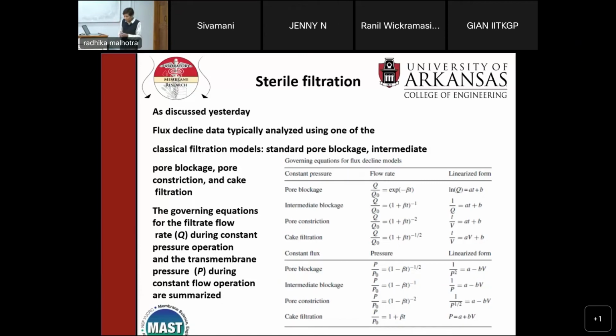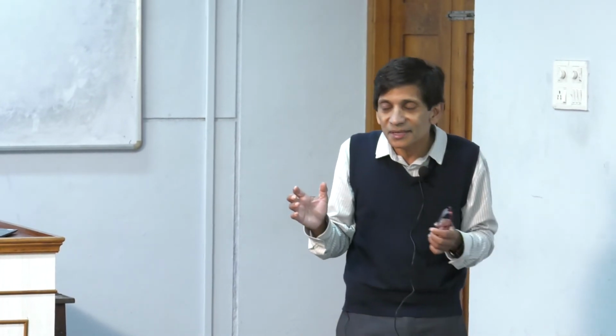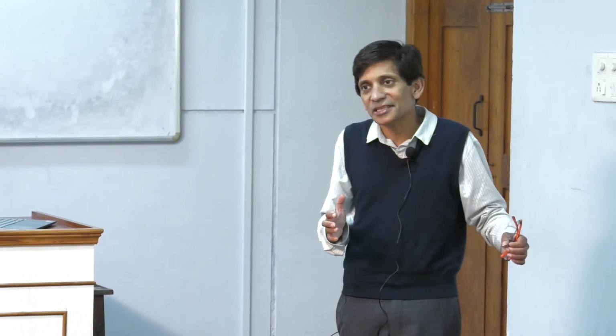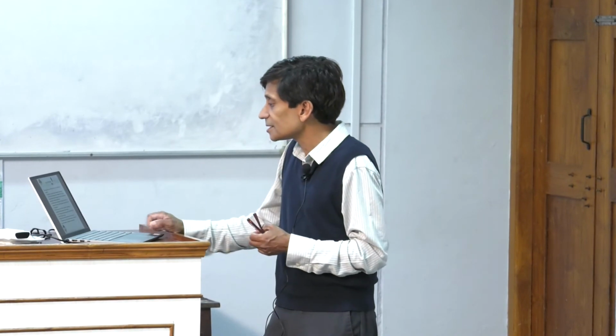Okay. Another thing to remember, in batch processing, you cannot change a filter during a batch. It's not sterile, right? It's impossible. So you have to size your equipment so that you can process the whole batch, because if you don't, you're going to lose the batch, and that could be millions and millions of dollars. That's huge. So often these are designed with a lot of redundancies, but capacity is very, very important.